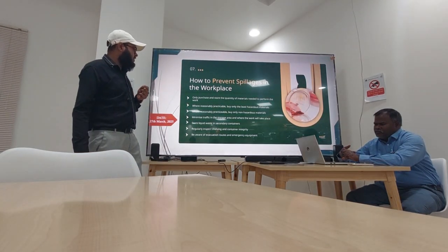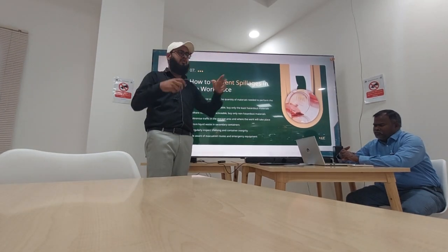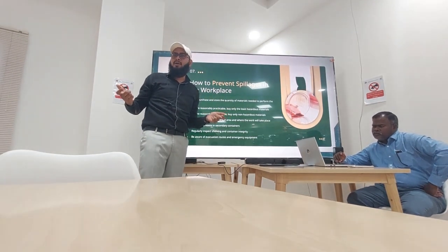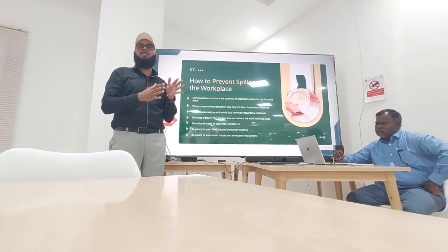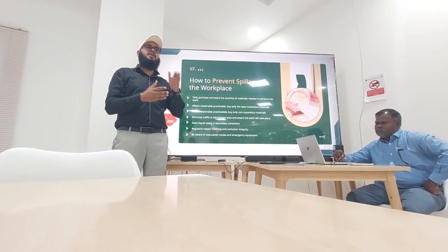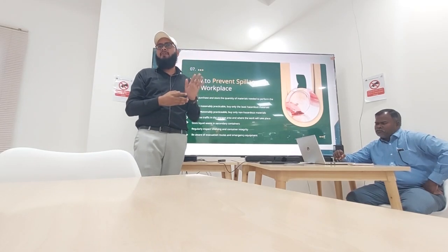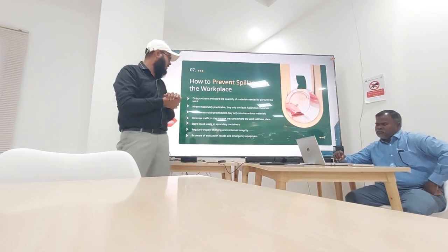Minimize traffic in the storage area. Traffic means don't purchase so much in huge quantity that you have no space and you are just piling up. We have seen this. Generally we are piling the chemical, which practically is not good. As per standard, any piling of any chemical or non-hazardous material should be not more than 1.5 meter, nearly 4.5 feet.